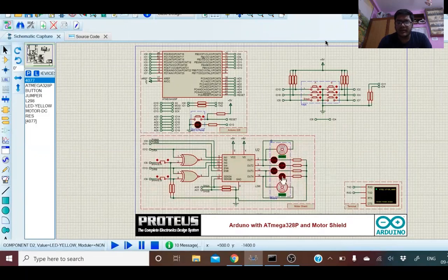For this part of the assignment, I'll only use motor 1. I have set the inputs as input 1, input 2 and ENA, and the outputs as output 1 and output 2. From the input 2 button, I can change the direction of the motor. If the value is high, it will rotate clockwise, and for a low value, it will rotate anti-clockwise. Now first I'll move to the source code.